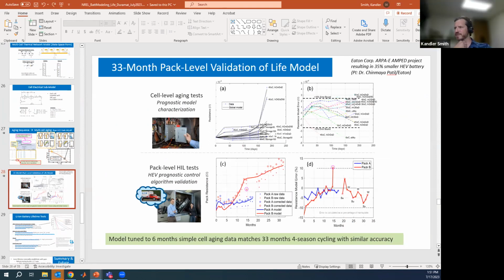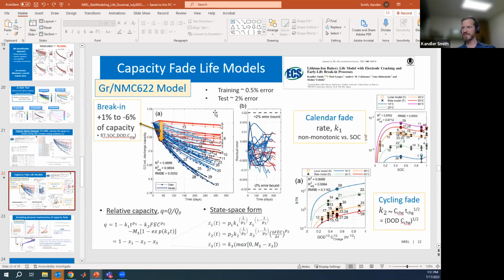Yeah, I didn't include material on some of that, now I'm realizing. Capacity fade oftentimes will be fairly benign early in life. All of these cases here have very graceful fade and follow kind of a square root of time trajectory until a point where there's an inflection point and things start to fade really rapidly. There was a review article one of the folks in our group participated in. I think they came up with 6 or 7 different end-of-life rapid capacity fade mechanisms from the literature.